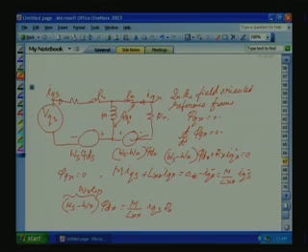So finally what we get? Omega slip into phi dr is equal to M by LRR into IQS into RR. Okay. So psi dr is constant. So that means omega slip is proportional to IQS, the orthogonal component. That shows phi dr is kept constant by keeping the ISD component, then omega slip is also proportional to IQS.